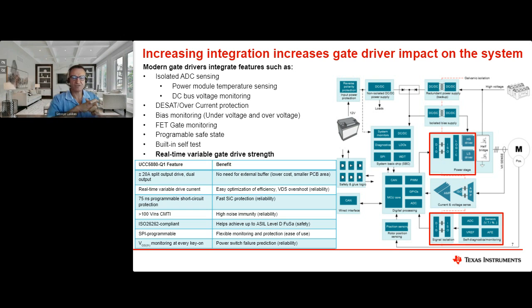It has very high noise immunity, over 100 volts per nanosecond. As I mentioned, it's fully ISO 26262 compliant, and that helps you achieve up to ASIL-D level functional safety. It comes with a 4 megahertz SPI bidirectional bus, so you can program into it and monitor out of it any parameter you want: overcurrent, overvoltage, undervoltage, overtemperature.